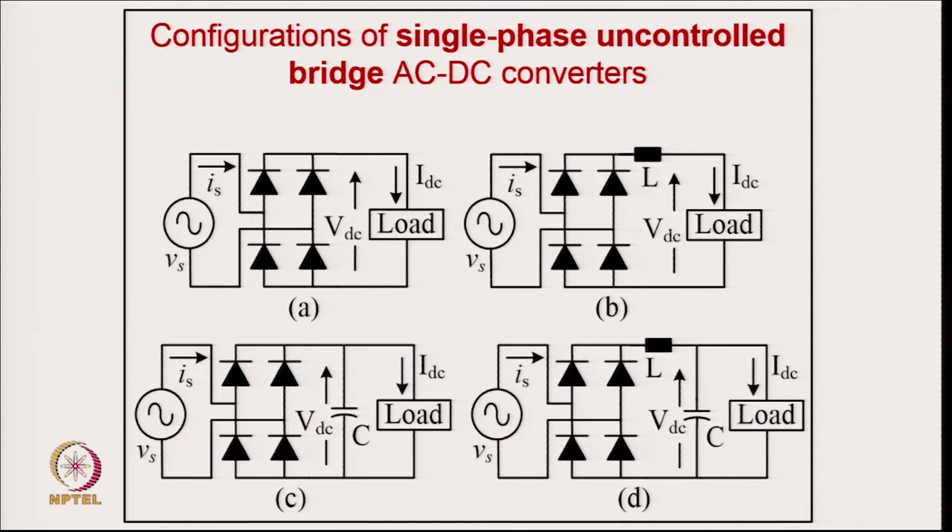Here harmonics are not so high, maybe a maximum of 48% THD. But here the THD goes as high as, in some applications like switch mode power supply, maybe 80 to 90%. Third harmonic is quite dominant, which also causes excessive neutral current, which we discussed in previous cases.